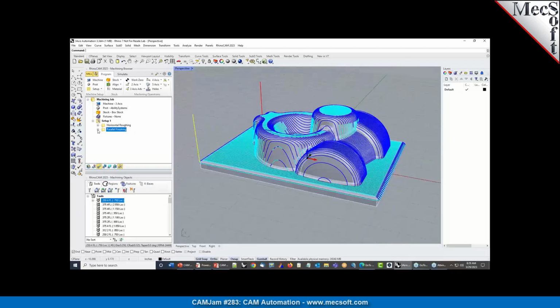And obviously you can go in and change any of these, save it back out to your knowledge base, and then keep building and building your knowledge base in that way. Now, this is just a base level of automation you can do in 3-axis. Obviously, you're probably going to want to select other geometry containments or whatever, but you can do this right at the base level automatically in 3-axis, regardless of what configuration you have purchased. This functionality is built right into the product.